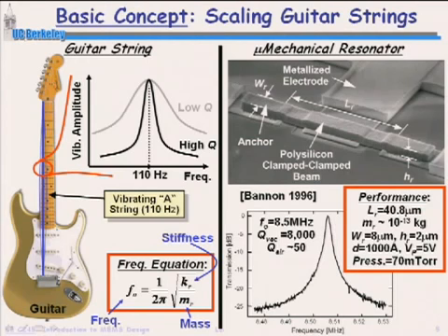So omega times M divided by the dissipation, which is damping, can be an enormous number in mechanics, whereas in electronics, it's not that big. There's a big advantage to going into mechanics if you have a technology that makes mechanical systems available, for circuits that want to select frequencies.